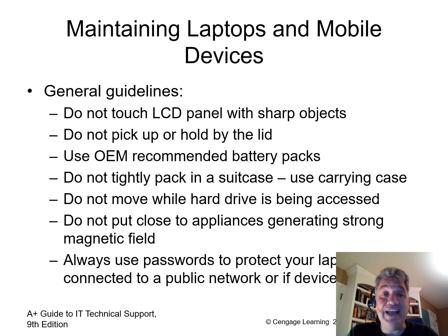So blowing the dust out, again, buying a can of compressed air and removing that dust buildup can be very important to extending the life of your devices. The dust will do things like, we'll use laptops as an example. As dust builds up on those fans, not only does it reduce the air throughput because it's just clogged with dust, but it also reduces the RPMs of the fan. So it's a double whammy in that the fan isn't spinning as quickly as it would if it were clean, plus it's not moving as much air through it. So it's very important that you keep those clean.